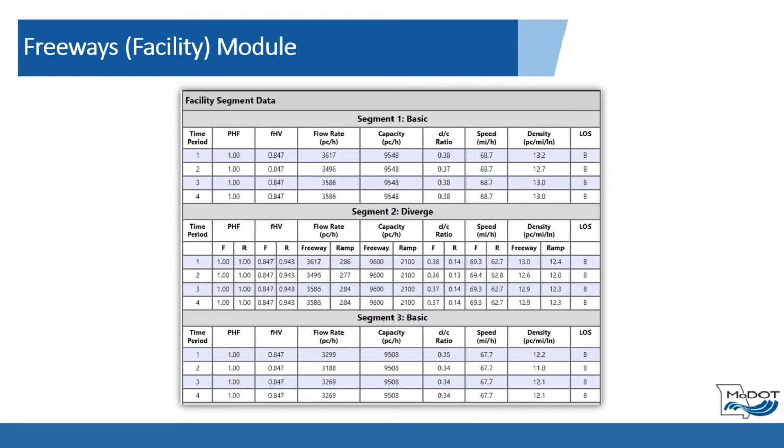The HCS Freeway Facility Module is recommended when studying a freeway corridor. It analyzes a freeway facility by linking the analysis segments of basic freeway, merge-diverge, and weaving into a single interface. Jam density and Q discharge values are applied to the string of analysis segments to determine potential bottleneck locations and adjust the capacity of adjacent upstream analysis segments to simulate the effects of queuing.